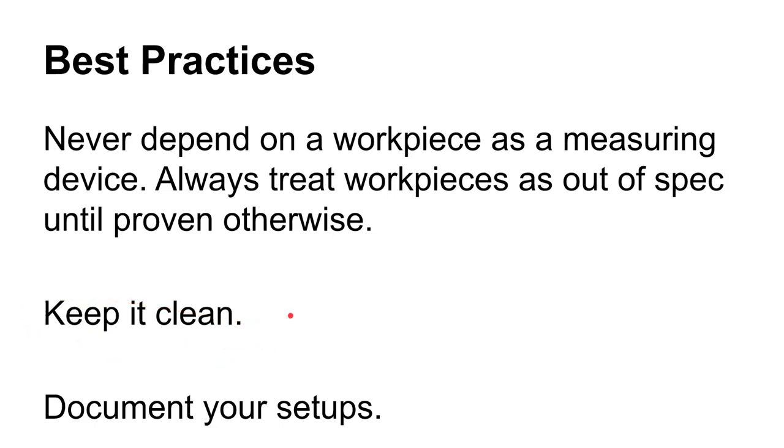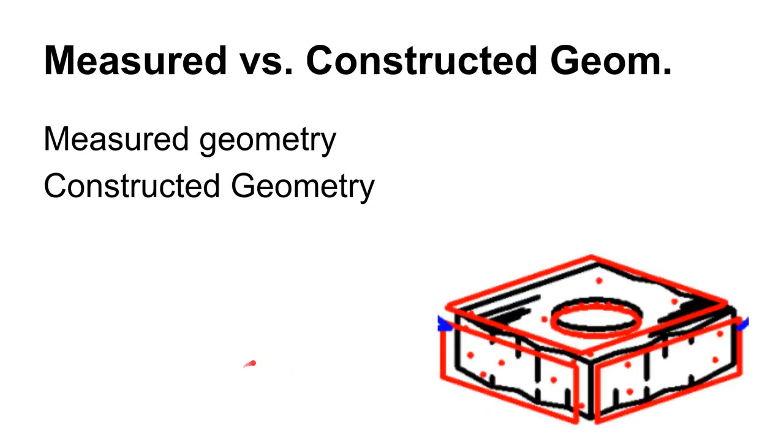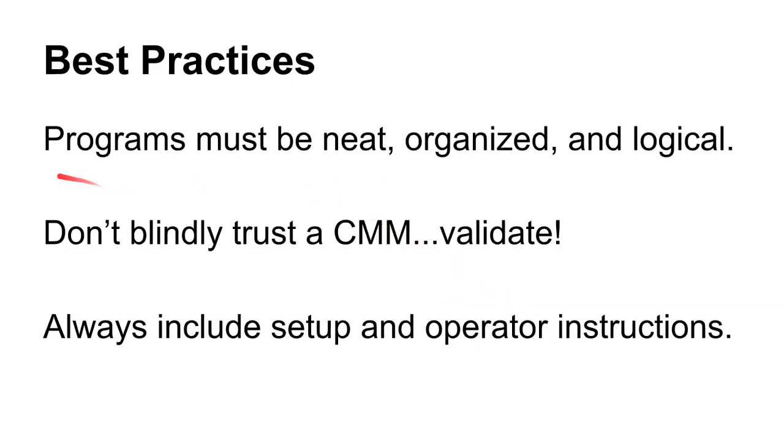You'll want to keep the setup clean, and you'll want to keep your programs nice and clean. All right, you want to make sure that everything's nice and simple, and for heaven's sakes, have everything documented. Don't just say things like probe the part. Say things like probe the part as documented in setup sheet number 1001 or something like that. You need to be very clear about where to probe the part, is what I'm saying. Make sure the programs are neat, organized, and logical.